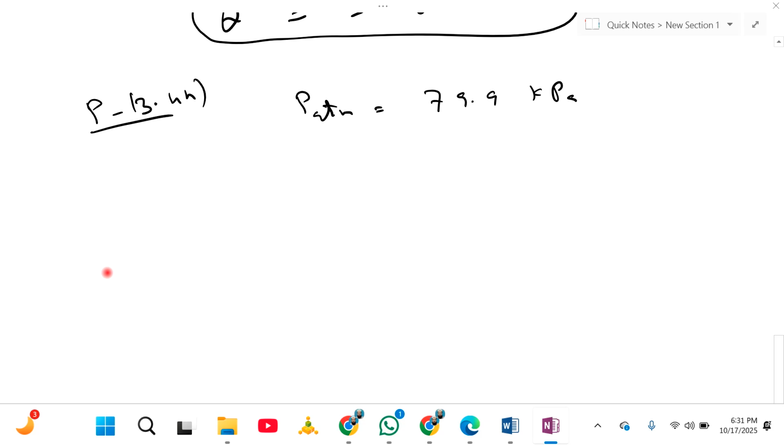So first we are finding saturation temperature or boiling point temperature at this value. So we need from steam table saturation temperature Ts, Vf, and Hfg. These three values are needed from the steam table.